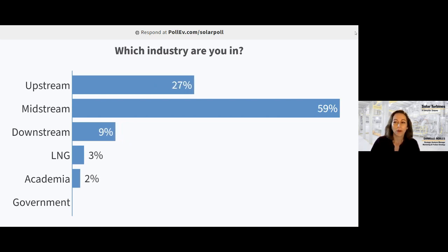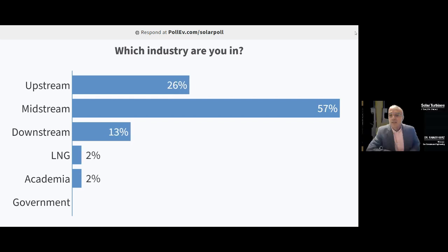What is the typical overhaul cycle for these compressor packages? Well, the compressor really does not have a specific overhaul cycle. If you run the machine with clean gas and you don't damage the machine, there is no particular overhaul required. The overhaul cycles are typically determined by the drivers, or in some industries, you overhaul your machines because you overhaul the entire plant at a certain time.